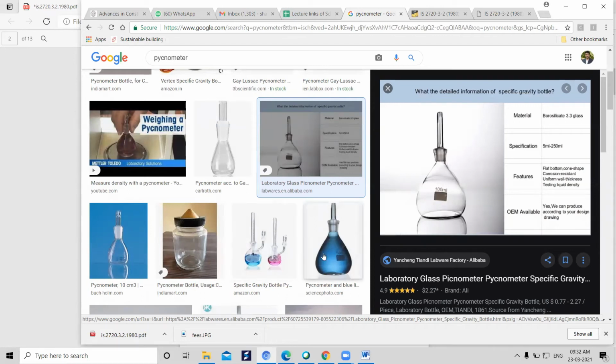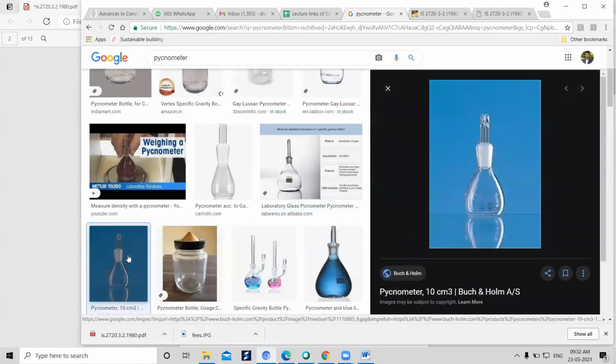Fine. Now why is it up at the top? You can see both the diagrams over here. Pycnometer भी देख सकते हो और density bottle भी देख सकते हो. They are with the inverted V like shapes, right? Why is it so? Because of correction of meniscus. Now what is this meniscus correction? Let me explain. Okay, you have two bottles like this. ऐसा कुछ दिखते हैं वो दोनों भी bottle तुम्हारे. Okay. You have a cap over here.